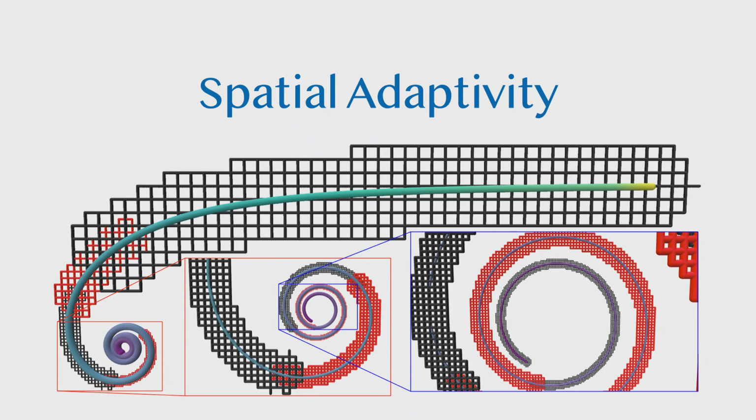For this spiral example, the smallest resolution shown in the rightmost zoom would have to be used over the entire spiral previously, which would lead to many unnecessary grid points and thus a bigger matrix system and a higher computational cost. So I'll discuss a way to couple overlapping computational tubes that have different resolutions, so we can have fine grids in some regions and coarse grids in others.